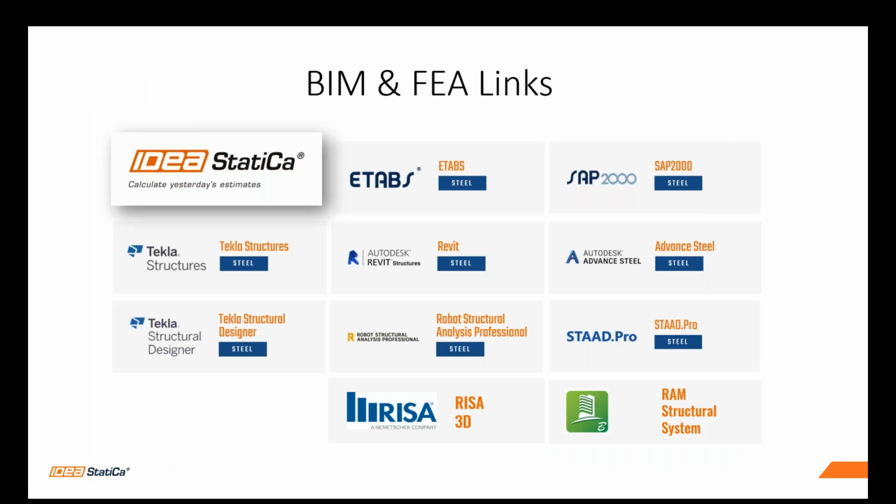So one thing I wanted to show, as far as linking to other software, I mentioned that earlier. You can see the usual players that we've worked with over the last couple of years. Two new additions are RISA 3D. From RISA, you can export an SAF file format, and that can be read directly into the Checkbot, which is our linking application to connect into IDEA connection. The challenge with that is that it is only going to be sending out the geometry and shapes sections. You will not get any loading from that SAF file format at this point.